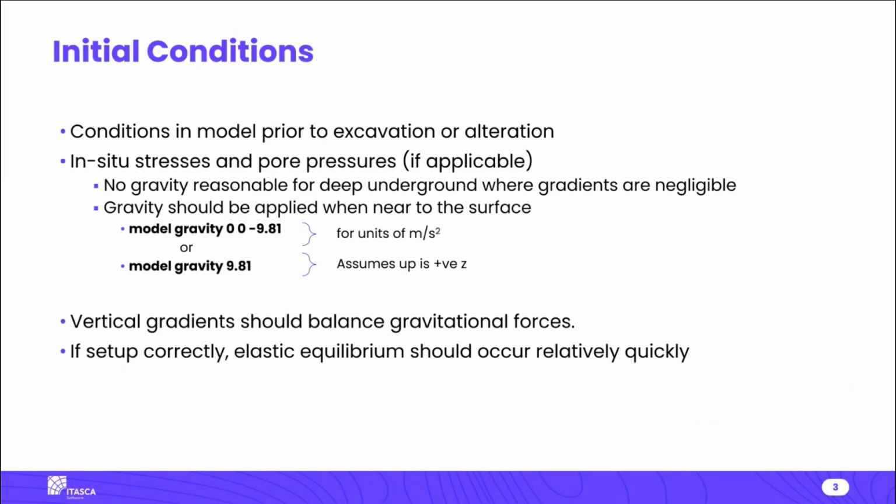We have to decide if we want to have changing stresses with depth, which is, of course, what happens in reality, but that may or may not be important. If you're very deep underground, the change in stress from the top of the model to the bottom of your model due to gravity is negligible compared to the stress in the model deep underground. So in these deep underground simulations, maybe you don't need to vary the stress with depth. If you're close to the surface, almost certainly you do want to vary the stress with depth and turn on gravity.